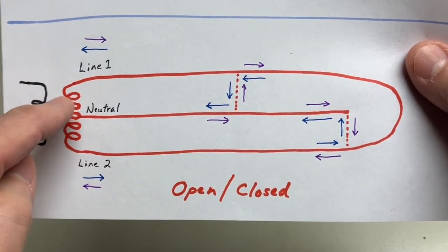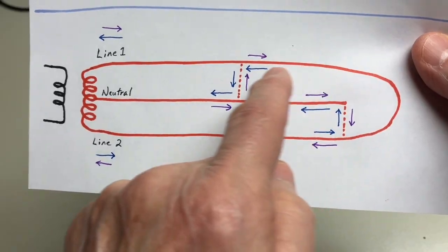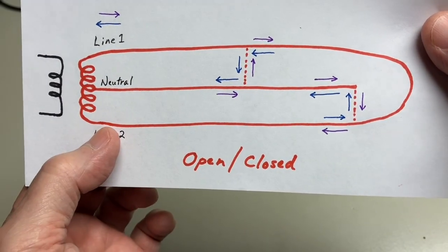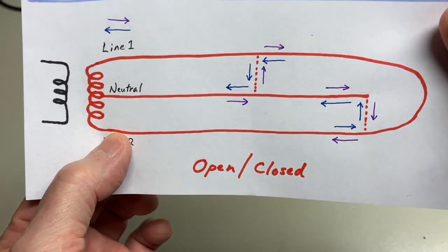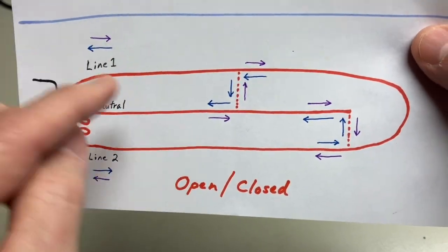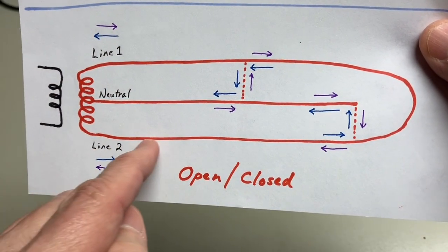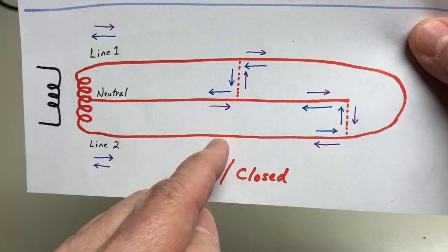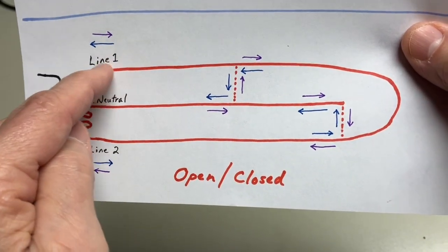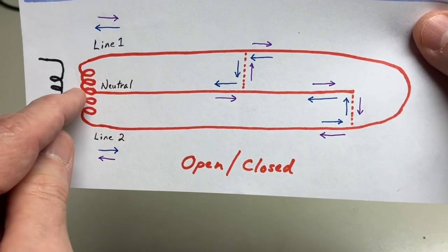All it is really is one long conductor, and it makes a loop. It makes a circle, right? It's only really one. Like you'd see in your panel, your black conductor, then you might see your hot red conductor, but it's all part of the same thing. It's just coiled up here. And when those conductors come off your transformer, it creates the illusion of you seeing two separate hots. And then you'll see the neutral. It's tapped into the center of your coil.